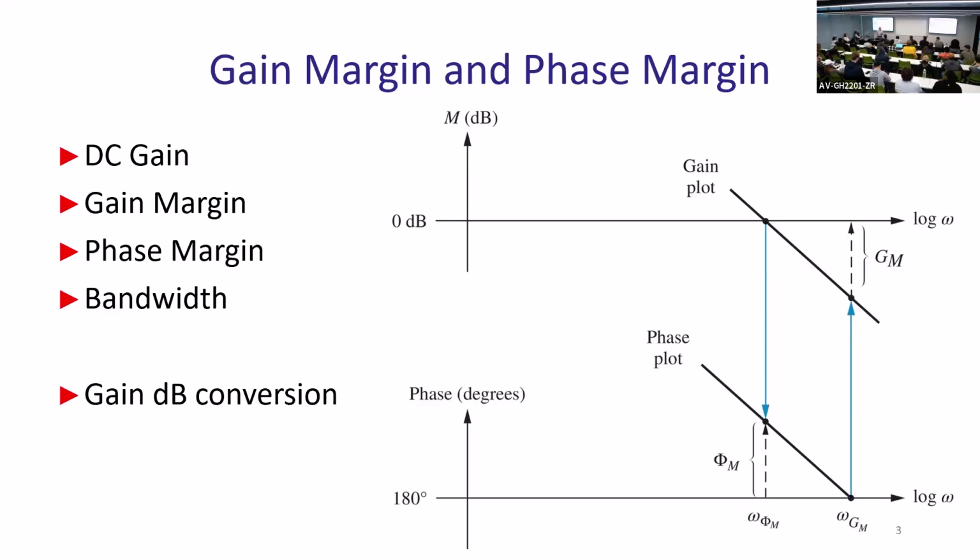Okay, so do you know how to convert from dB to regular gain and from gain to dB? We started to talk about that a little bit. Number one, 20 log gain is gain in dB, but how do you get back? It's 10 to the power of gain in dB divided by 20. This is how you solve it backwards.